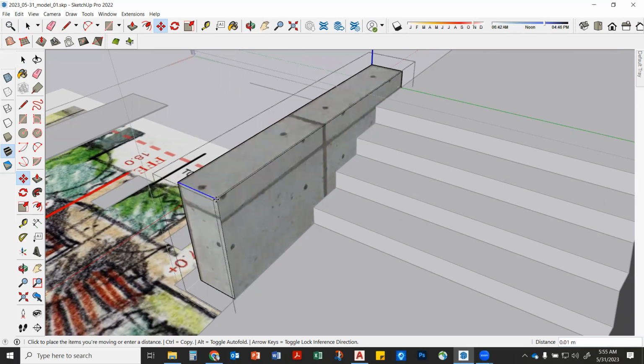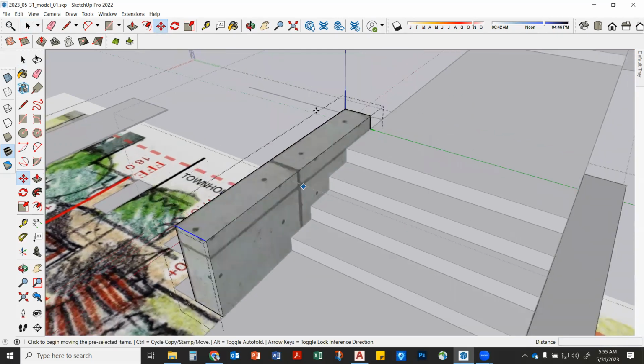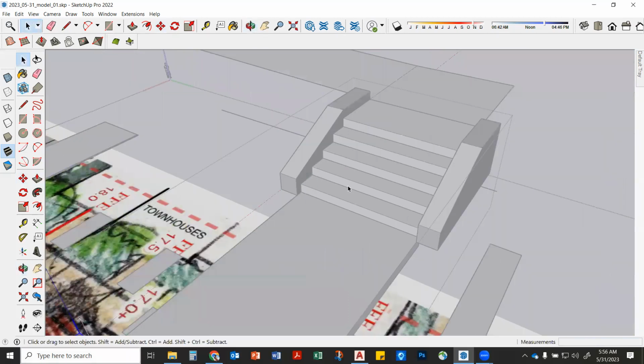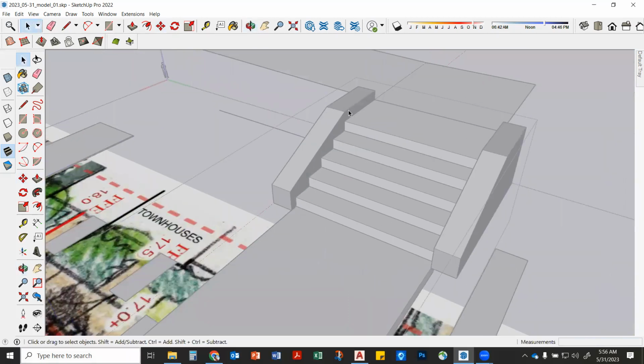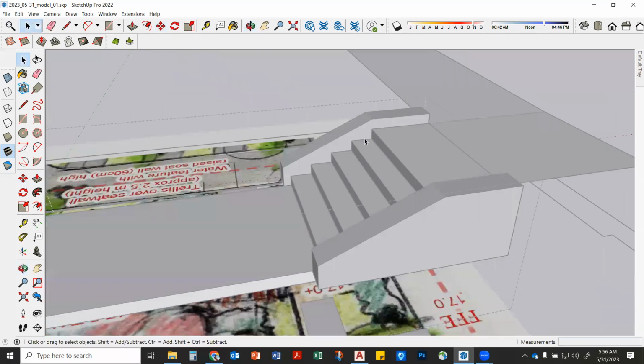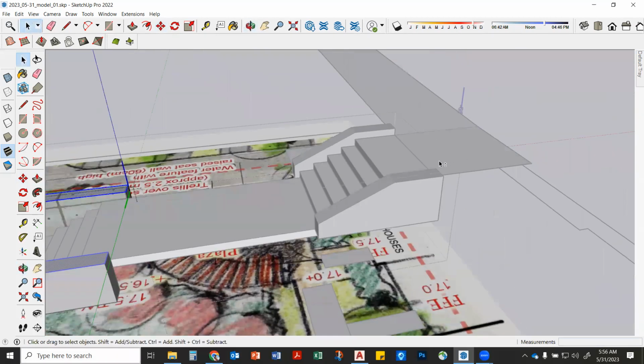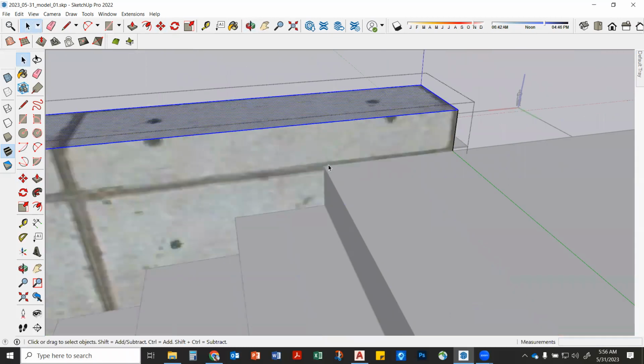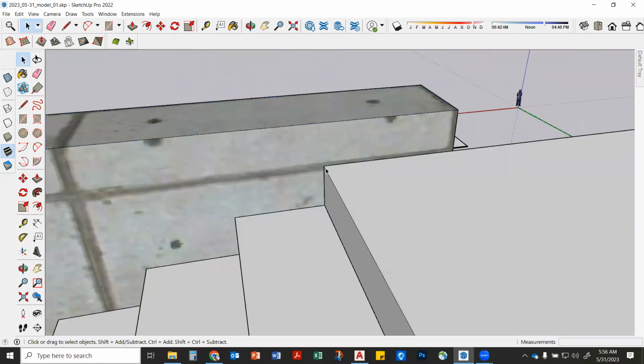But the way we did it up top is we added another line up here so that we could break that face, right? Because right now this face up top is what's moving, right? We want to slope break about midway, right where that stair is, that top stair. Let's do the same thing here. Let's find that top stair, top riser.